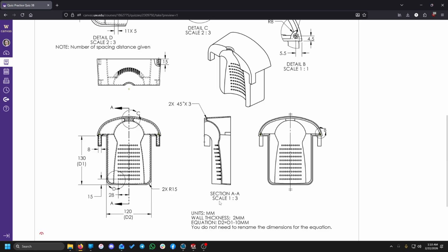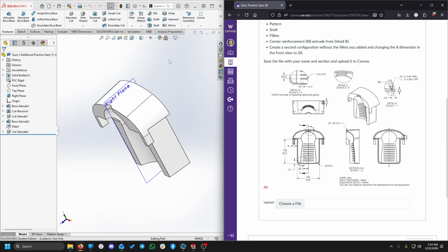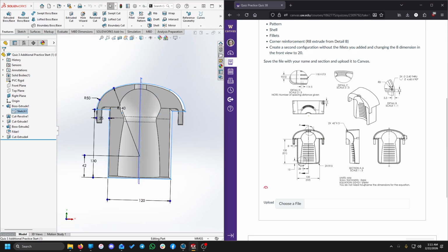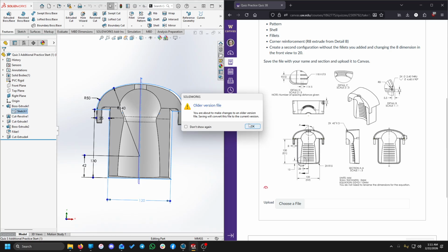The equation is using dimensions that are already used within our object, so we can actually add that right now. It's usually not a bad idea to do the equation early, just because it's easy to forget otherwise. So this one says that D2, which is that width at the bottom, is equal to D1 minus 10 units. So D2, this 120, is equal to D1, the 130, minus 10. So if we...